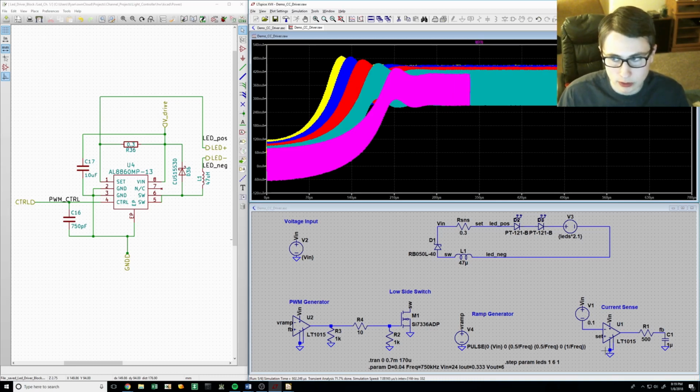This, while it may look like an op-amp, is actually a comparator, which is a lot like an op-amp but optimized for railing one way or the other when the condition where it would go high or low is met. In this case, when the positive input is higher than the negative input, it will turn the output on. And when that condition is not true, it will turn the output off.